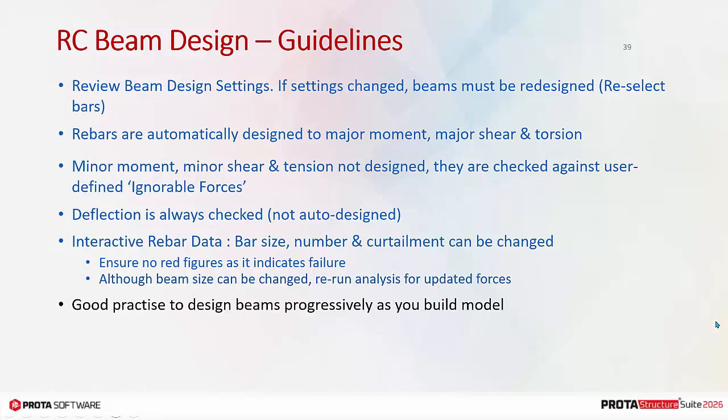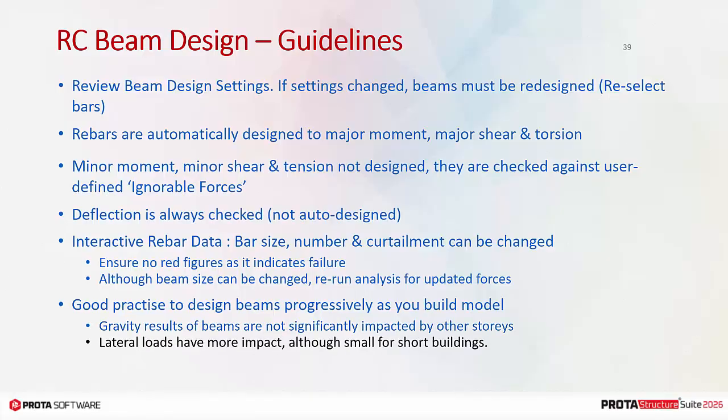It is good practice to design beams progressively as you build the model. Gravity results of beams are not significantly impacted by other stories. Lateral loads have more impact, although small for short buildings. Use the filter function to design in small batches, for example by story.